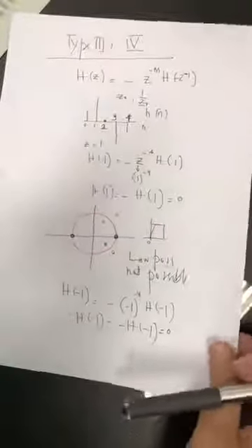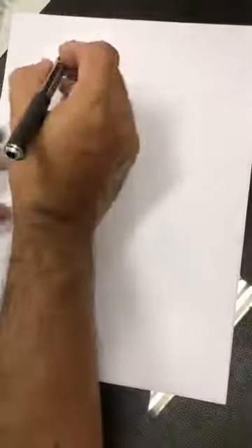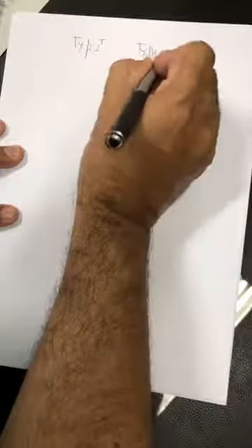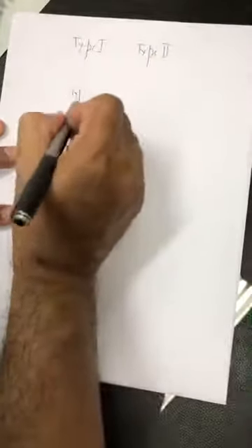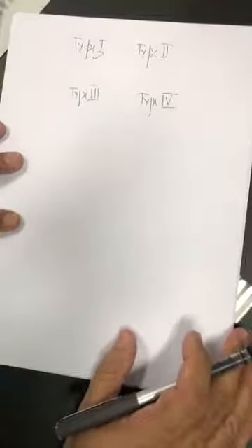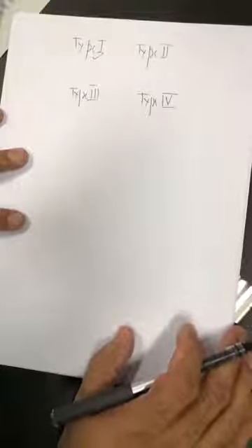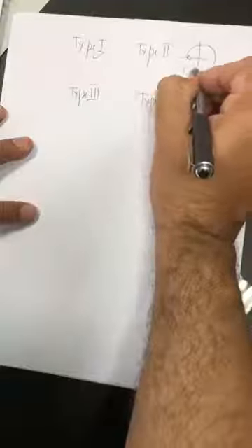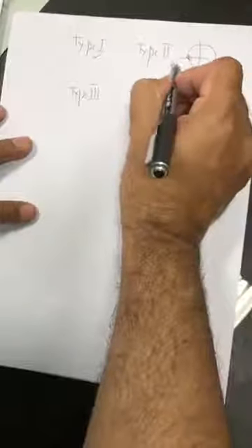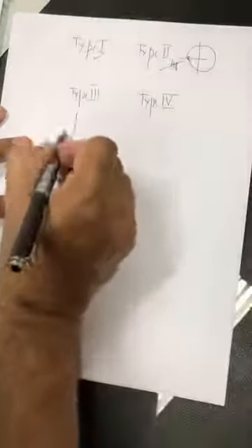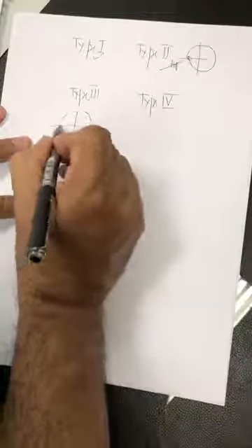So once you put all these together, type 1, type 2, type 3, type 4: there is no problem with type 1. You can have all kinds of filters as type 1, because as a consequence of symmetry, it does not force a 0 somewhere. But type 2 forces a 0 here, so high pass is not possible. Type 3 puts a 0 here and here.